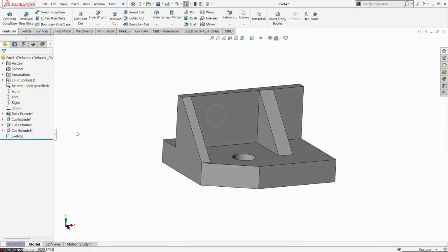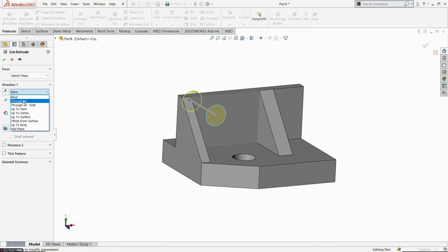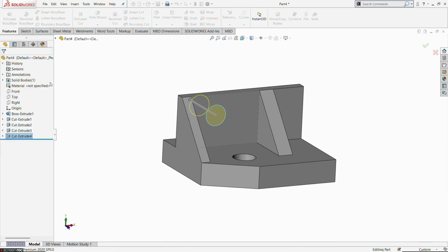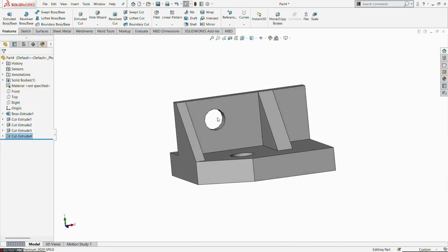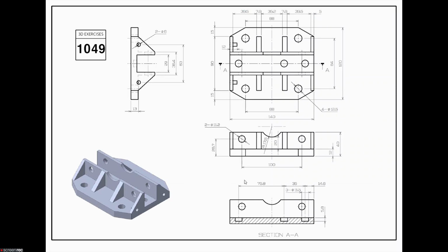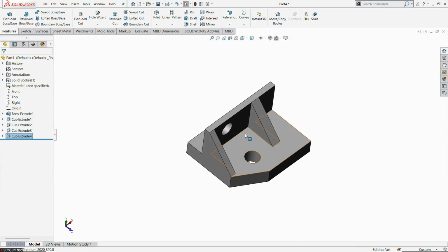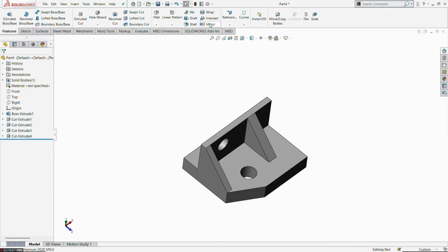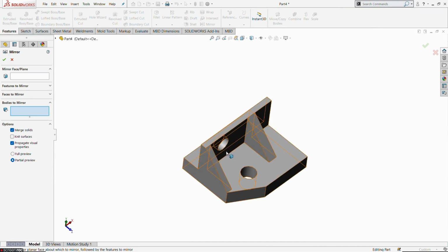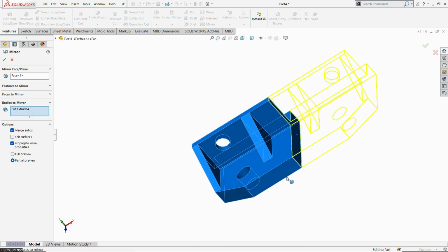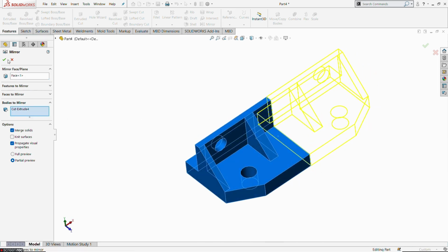Afterwards, make a pocket by using these profiles. So select the profiles, using extrude cut, create a pocket up to the next of its portions. Cut the entire body. Okay, let's mirror the portions at a different area to cover the entire solid part. So select mirror and choose bodies. Under bodies, select this particular body. Also verify the merge result because it combines the entire body between that.